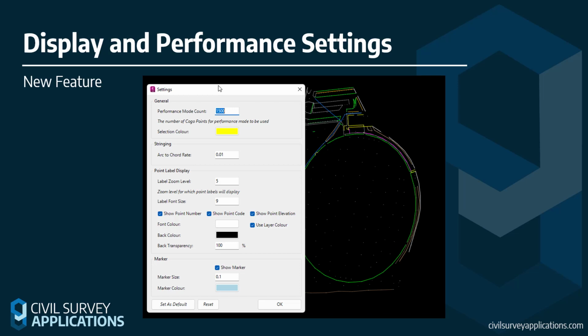You're able to choose a selection color, arc to chord rate, a number of other features to improve the speed and adjust the display of your points within the survey line manager and the 2D viewer. Both of those are influenced by this. The DWG itself will not be influenced by this display, so keep that in mind if you're running through it.